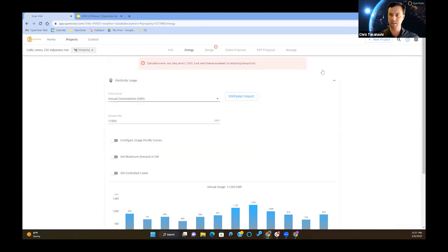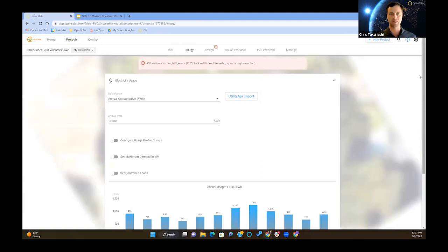I am in the energy section of this project, so I want to highlight and touch on further what Orion has mentioned about knowing your energy, knowing the energy consumption patterns of your customer. That's really going to be key for knowing if certain time of use rates are ideal, if storage is necessary, right? If it's a homeowner that is mostly home during the day, they're cutting lights off and not using appliances in the evening, maybe a retired couple fits that profile, storage may not make sense in that situation. However, for a lot of folks, storage is really going to be that key input needed for better long-term savings.